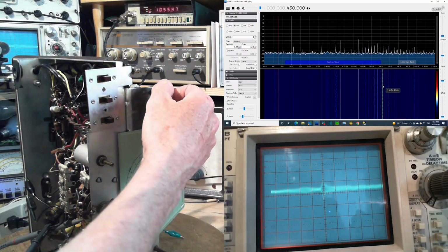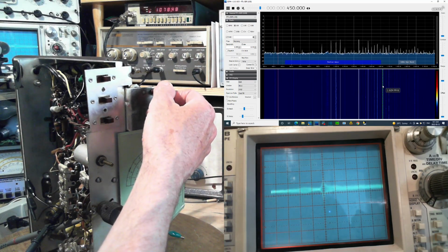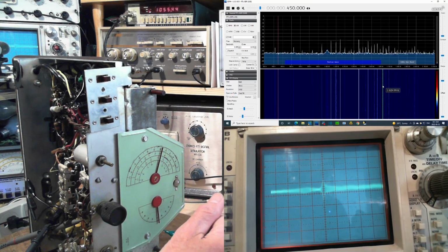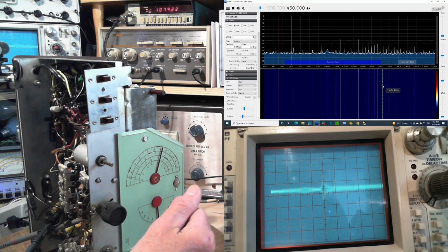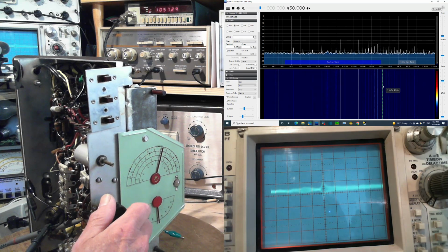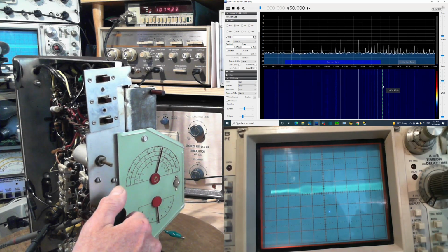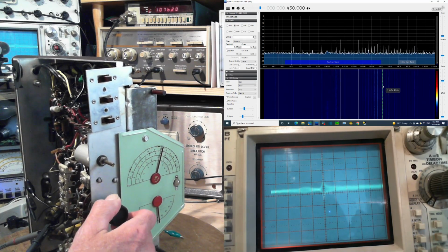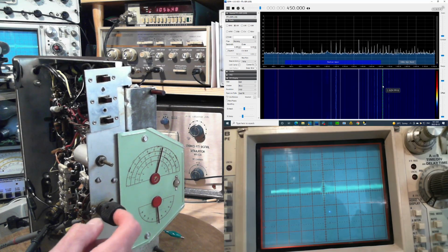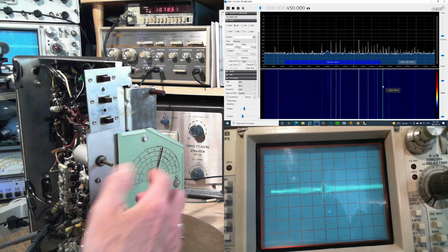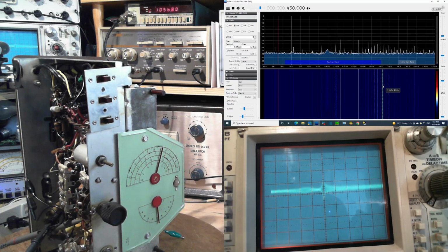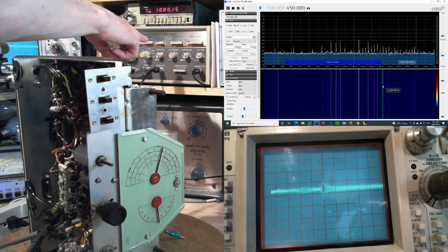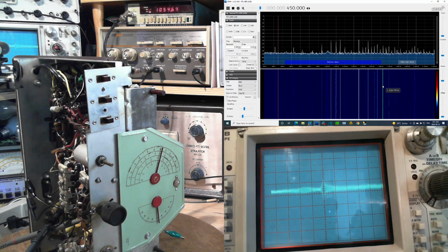Now we're going to tune around. Is that what I want to do? Tune around? Turn some other controls? What else could make a difference? Band switch. Well, you see the front end peak when you're in the same band as the frequency. So this is the broadcast band. Peak of what? Peak of the scanned signal coming from the signal generator. When it goes past 1,000,000,